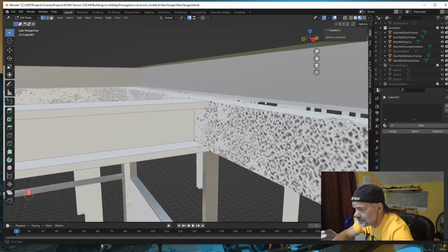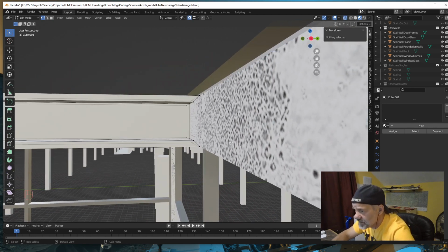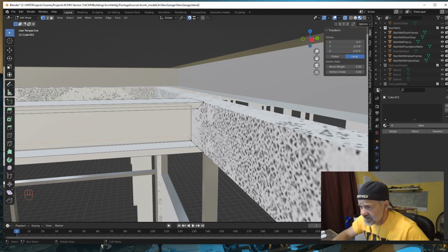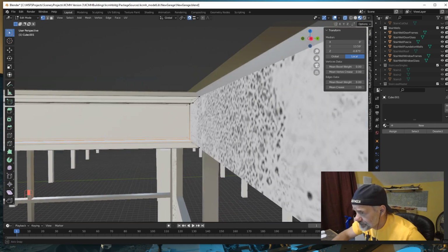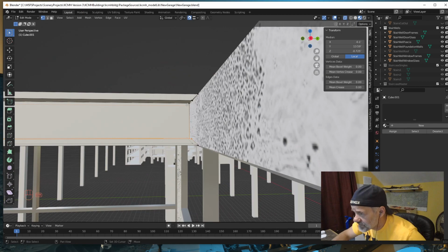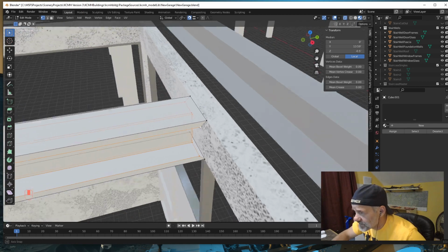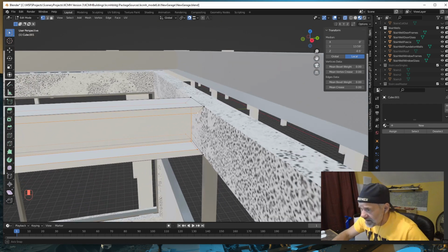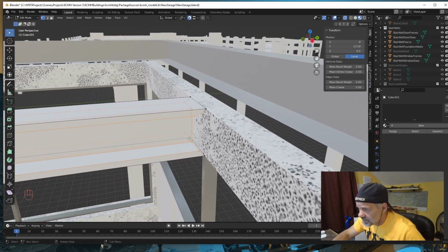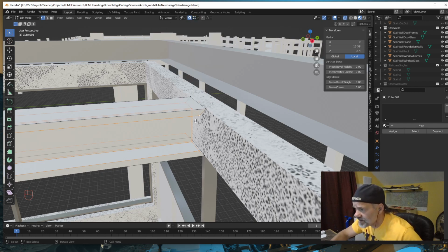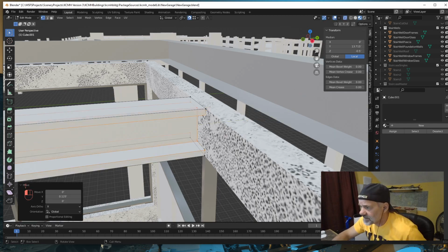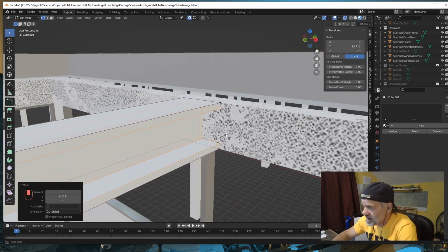Then I'm going to vertices select, and I am going to turn ghost mode on, and I'm going to select these vertices right here and these vertices right here. Hopefully I didn't get that one over there. Okay, so I have these vertices here, and I'm going to move those in this direction so they line up with these. All right, so vertex select, snap on, and move those in the Y, and click on that. So that gives us our I-beam, just like that.